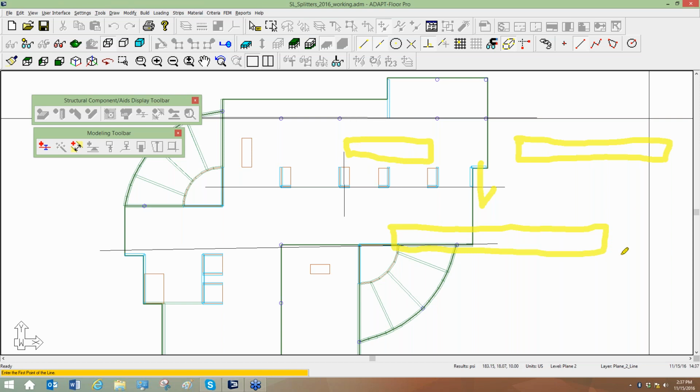And the program takes this cut, which is called the idealized design section. It calculates the centroid. It finds the moment, the shear, the axial force, whatever other sections at this centroid. It designs for these actions.